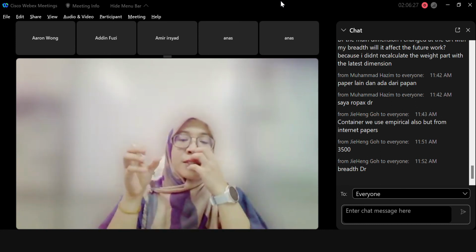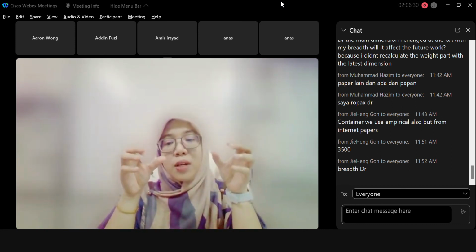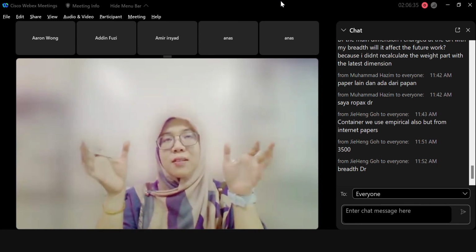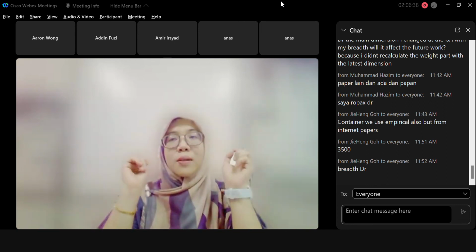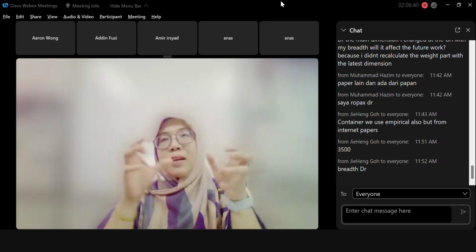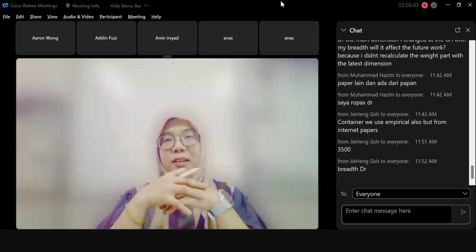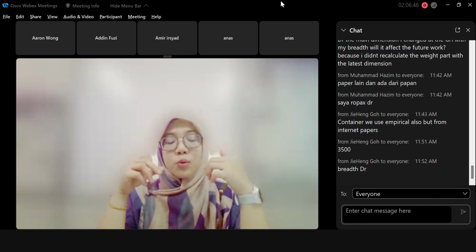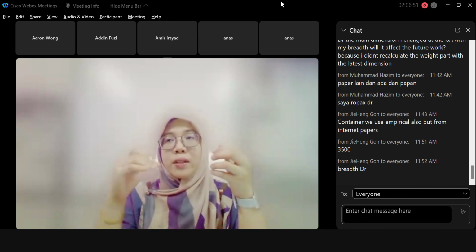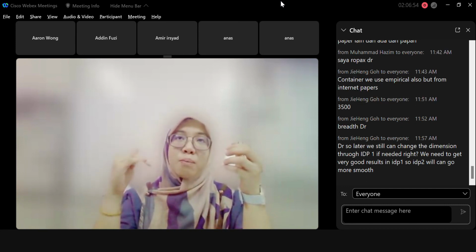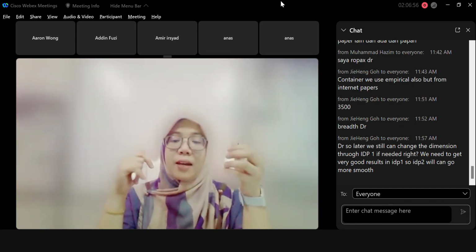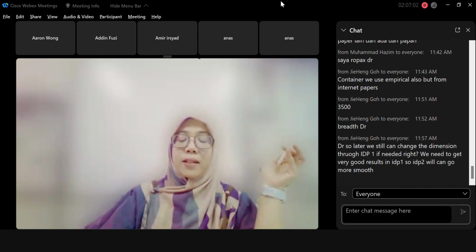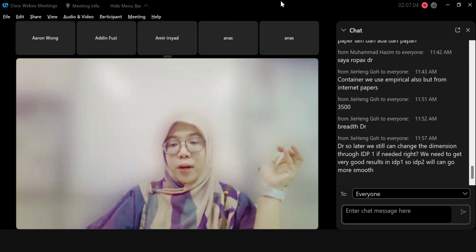Then they put it in the initial GA to see whether they can accommodate such a number or not. Same with those with row packs, 1,000 passengers. They have this cabin, they have this sitting area and so on. Then they do a capacity calculation to see whether with that size and the number of decks, they can accommodate the number given by the owner, on the owner's requirement.